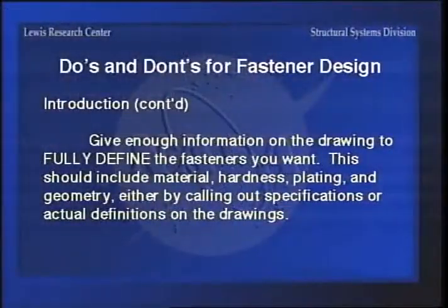And I know in the past I've been disappointed in some of the drawings in which they say all fasteners to be per FF-S-86 or 85. Now if you go look at that spec, you can get anything from alloy steel, stainless steel, down to even nylon fasteners on it. So you're giving the guy a lot of leeway if you don't define it any further than that.